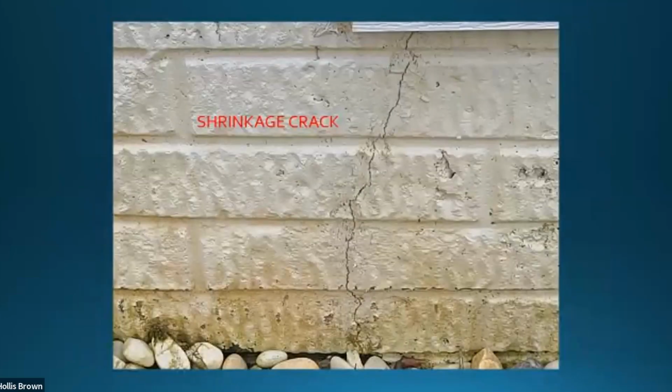I'm gonna move on. There's an old saying about concrete: if it ain't cracked, it ain't concrete. Most of the time, in fact, I would say almost all the time, when we see cracks in residential concrete foundations, believe it or not, they're shrinkage cracks. It's just that it wasn't cured properly. It dried out too fast, and that's usually when you get shrinkage cracks.